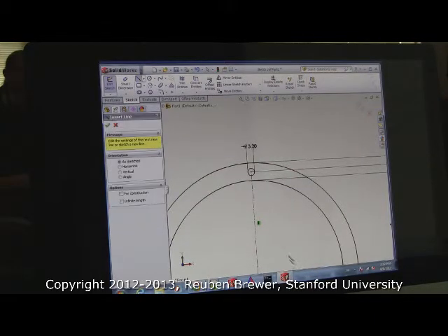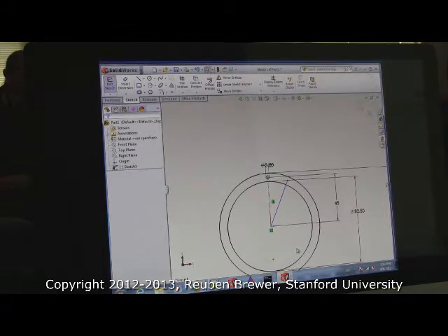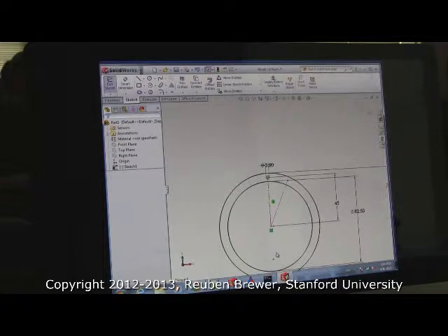So everybody watch me for a sec. I selected the wrong line, and that line is solid. Click on the line, and then on the left, you hit For Construction, and it's converted. So anytime you draw a solid instead of a dash, or a dash instead of a solid, you can always use For Construction to change that.